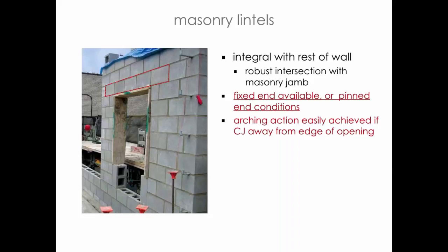All right, so masonry lintels do have the inherent ability to arch over the opening. If you have an arched doorway, you in fact don't need any reinforcement, no steel within that opening, right? You saw the early pictures. We can do this. We can do that for a long time in a concrete or a stone type of material. Built in place or prefabricated.